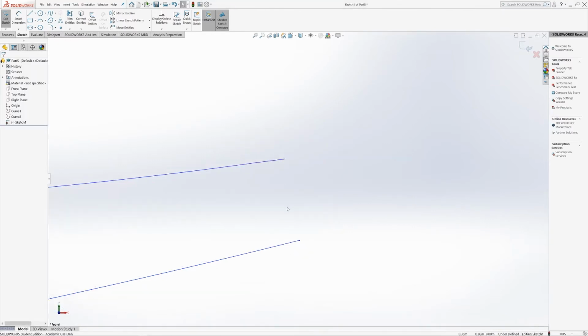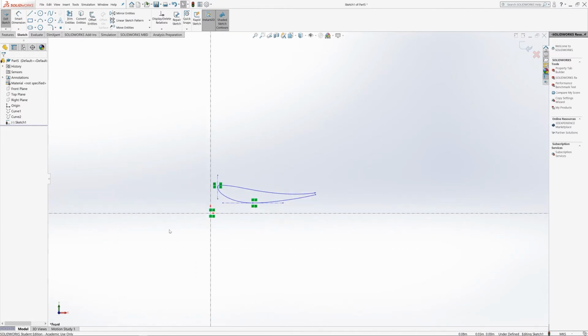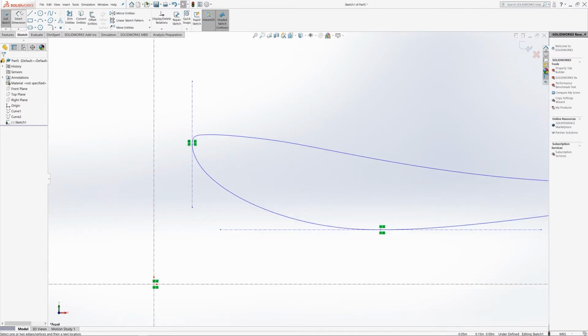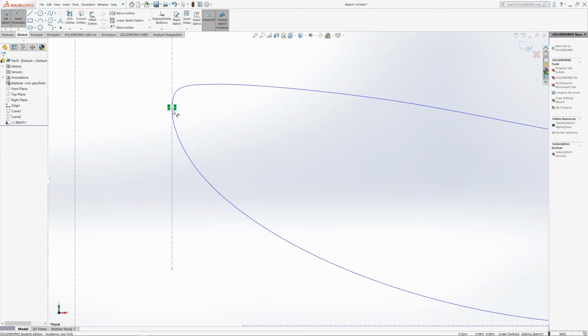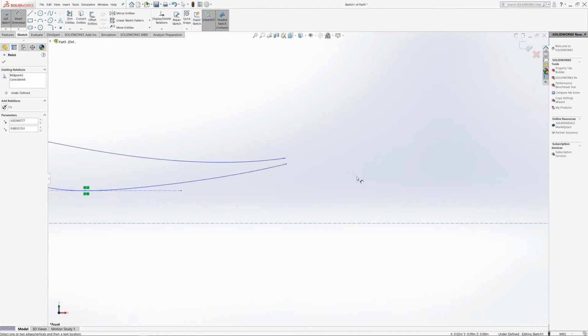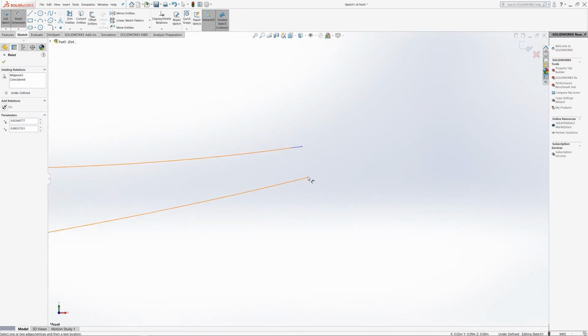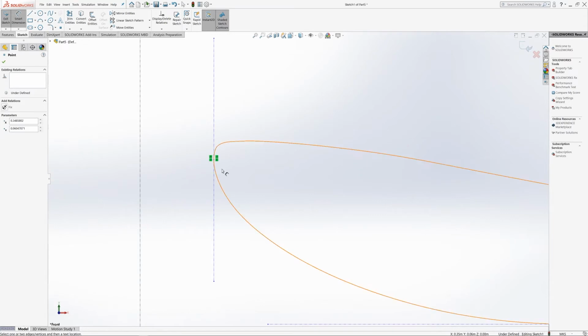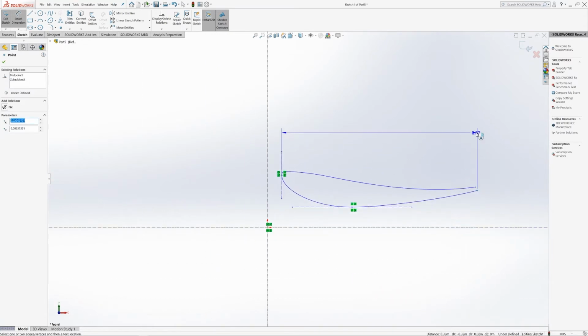Yep, click yes. So we've got our open aerofoil here, and I'm going to dimension the aerofoil now. This part is the least accurate in terms of the whole process. Delete this line as well, my bad. Okay, going to delete, and I'm going to smart dimension between there, make sure that you're dimensioning the chord and not just the horizontal distance.